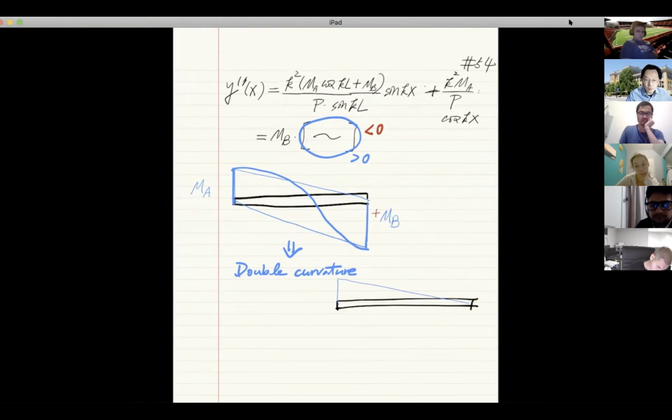So how do you express a negative MB? You just flip it. So here, downward here, there used to be the positive MB. To make it negative, that means you will have to change the sign. When you change the sign, it will be flipped to where? To the top. That means this will be where the new MB is going to be.